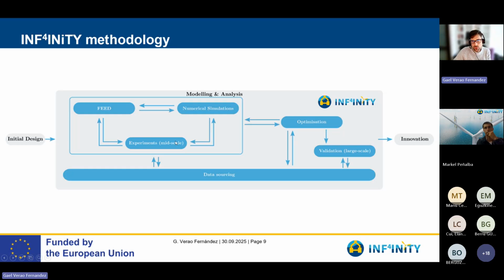And this is where the seminar of today comes in: how we are defining the design load cases that we use as input parameters. Our case study, or the boundary conditions for our design, is that we are trying to achieve a design that can hold at least a 12 megawatt turbine. Currently, we are making numerical simulations with a 15 megawatt turbine. And then we want our design to be feasible for the Mediterranean, Baltic, and Scottish seas.